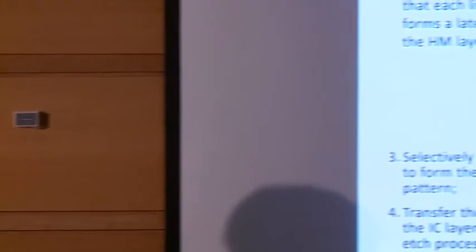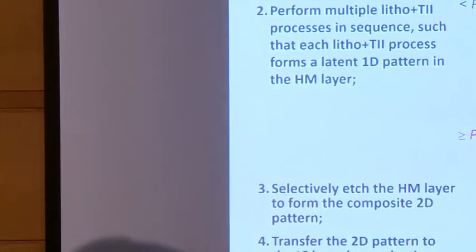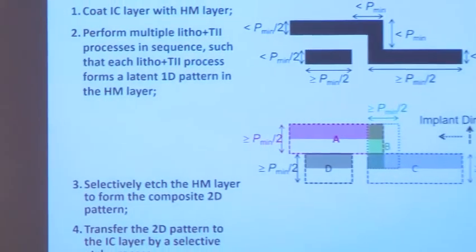But with this approach, the idea here, if I didn't mention it clearly, is that each of those lithographic masks is subcritical in terms of feature size, right? It's just a normal 193 stepper. It can be used to define each of those patterns.